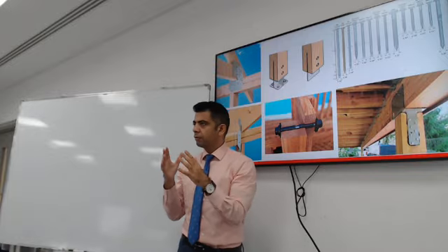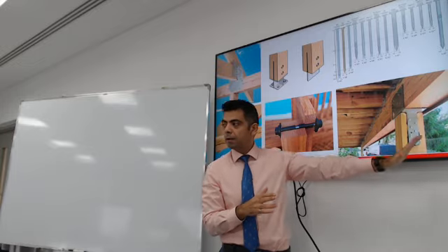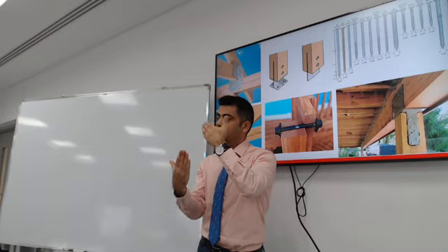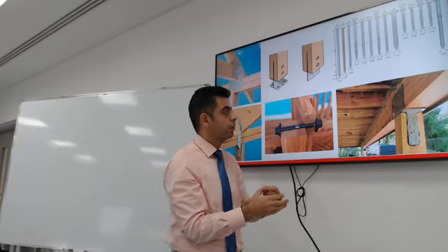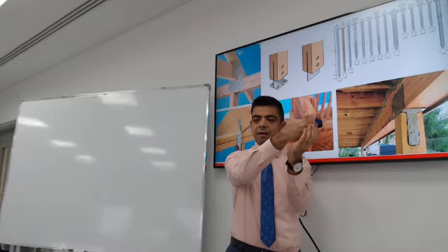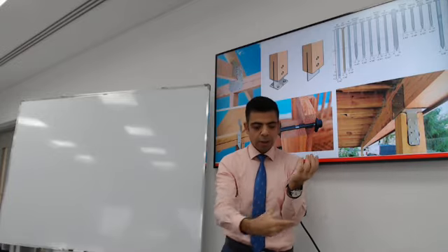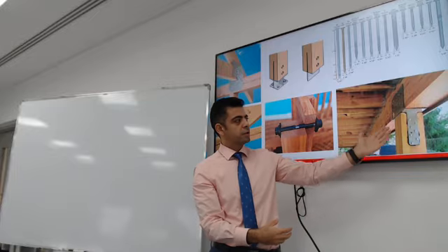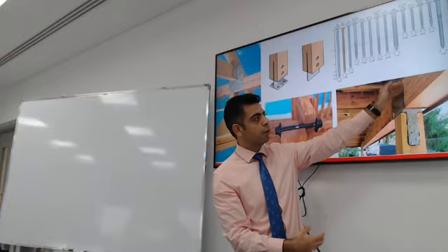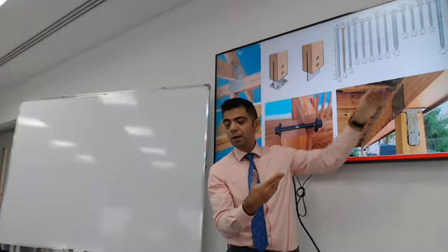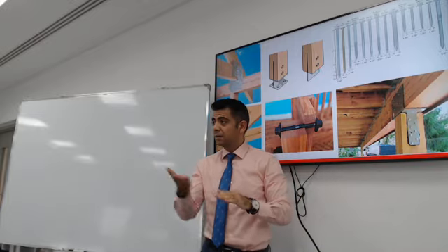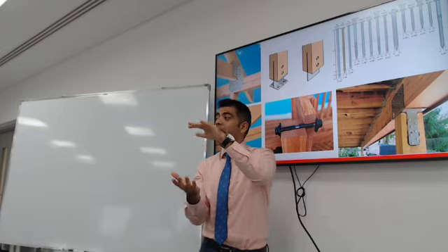Or if you want it just for practical reasons, if this is all going to be covered up, you can use steel accessories or ties to connect wood pieces together. For example, this is called a saddle. The beam is sitting on the saddle and it has these two sides over here to be connected to the column. So that's an interesting way to have a beam-column connection. You can see how the beam is made out of layers. This is sawn timber in layers. I can count maybe 5 or 6 different layers. You use them together as a beam.